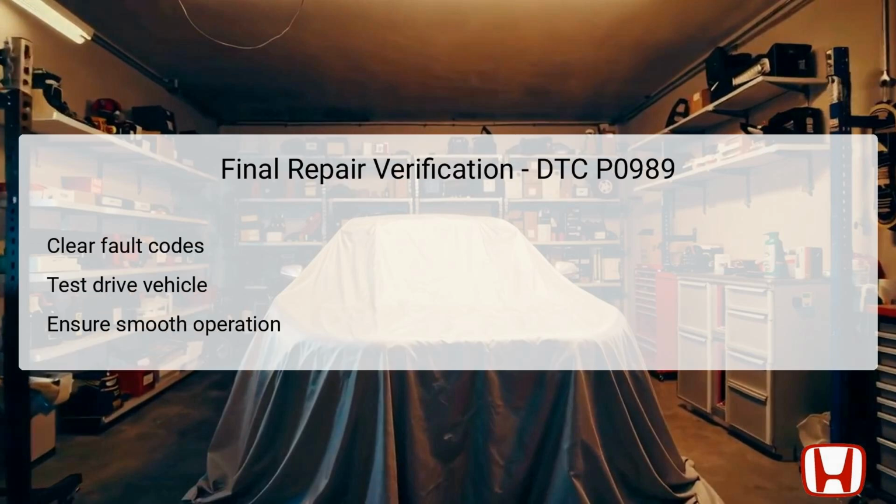After completing necessary repairs, the final verification step is crucial to ensure that the issue has been resolved effectively. First, it's essential to clear any fault codes stored in the PCM to reset the system. Following this, the technician should conduct a test drive, replicating the same conditions under which the DTC was originally triggered. Monitoring the vehicle for proper performance, especially in shifting through the gears, is vital in this phase.